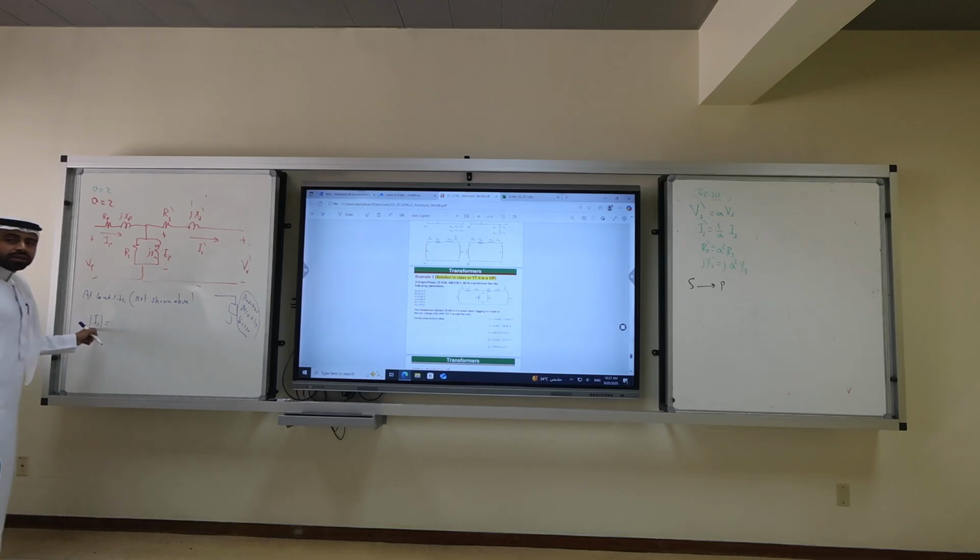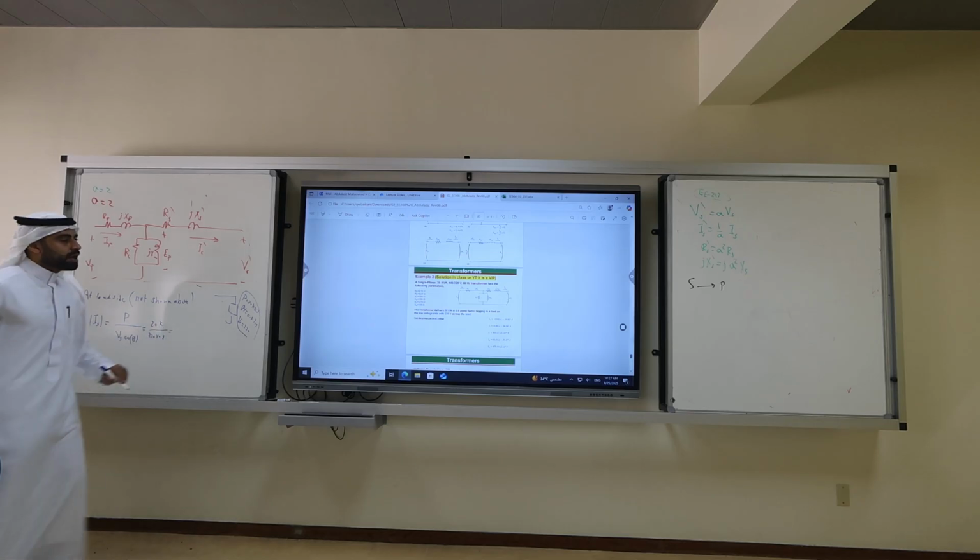What is Is magnitude? Is P over. Do I need to divide by 3? No, because it is single phase. Divided by Vs times cosine theta. What is 20 kilo divided by 220 times 0.8?